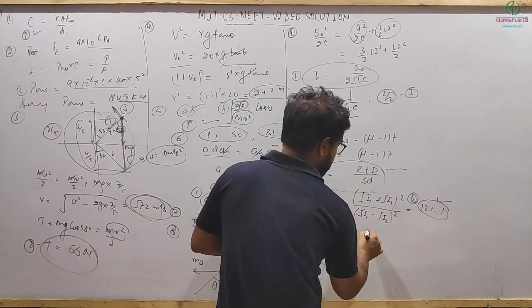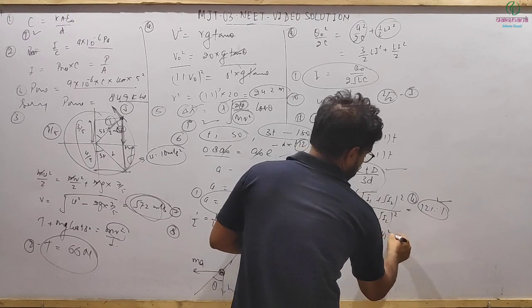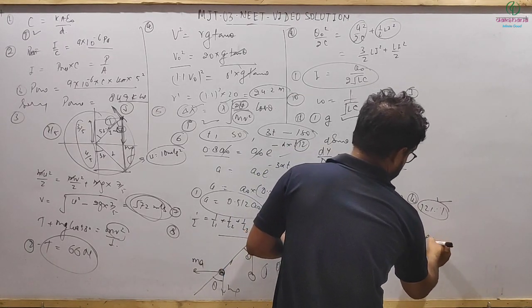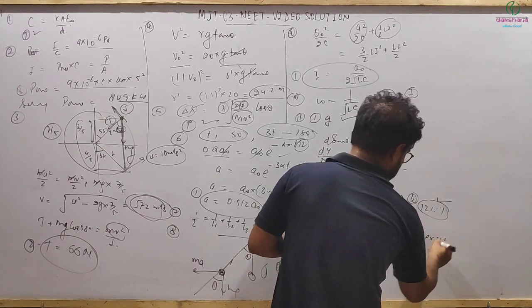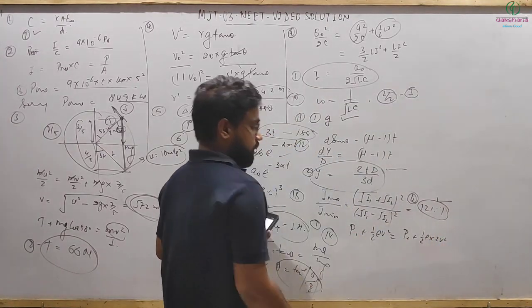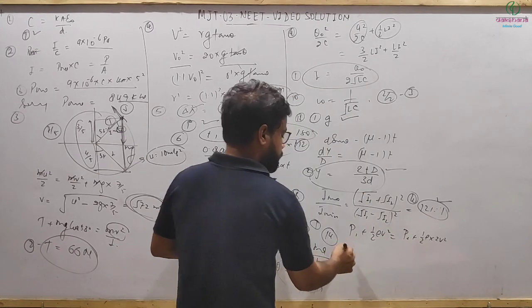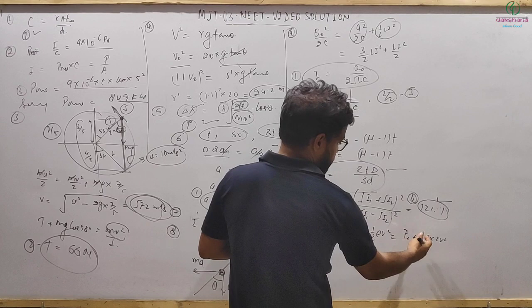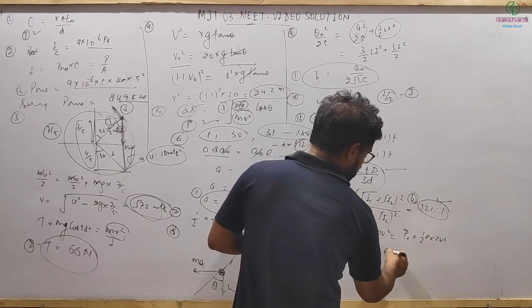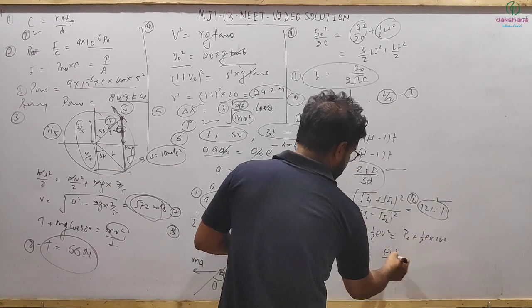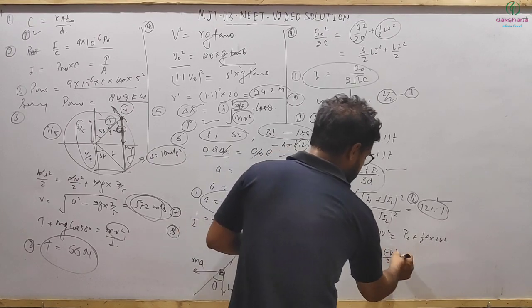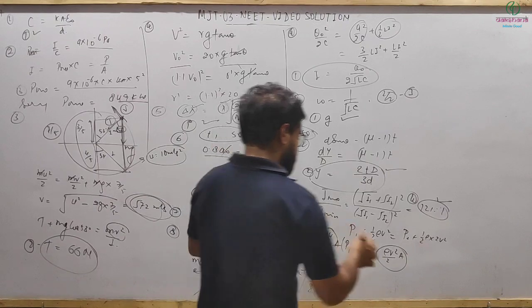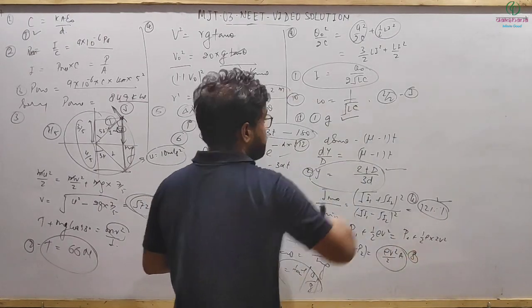So it's P1 plus half rho V square equals P2 plus half rho into root 2V whole square. Here the pressure will be low on top, so P1 minus P2 can be written as, this is basically 2 minus 1, so it's rho V square by 2. The pressure difference multiplied by area A will be the lift, and that's matching with option number 3. Next, question number 15.